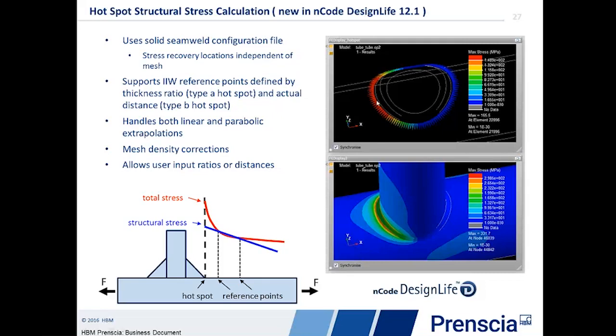And what you're seeing in the top display is actually our post-processing of, in this case, the max stress, but again, we pull out things such as life and damage as well for the weld. The markers that you see, their large end is the location we're doing the calculation, and they extend out, showing you the linearization path that was used.